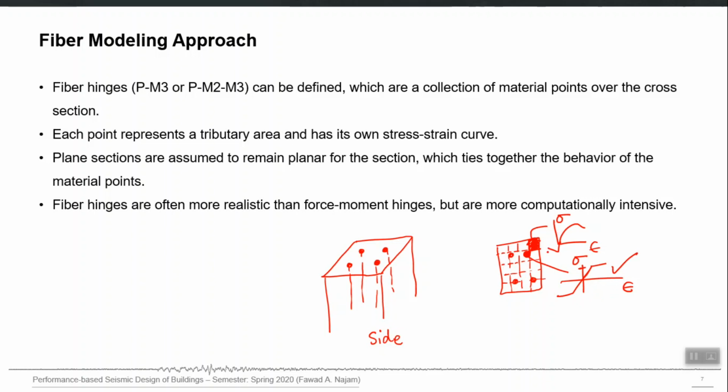Ultimately, with this hypothetical cut which I just drew here, 1 2 3 4 5 and 1 2 3 4, it is actually a 5 by 4 mesh, right? So it's like 20 concrete fibers with 4 steel fibers. So with this cut I am actually saying that this cross section is made of 24 fibers. 20 fibers are concrete and 4 fibers are steel, right?